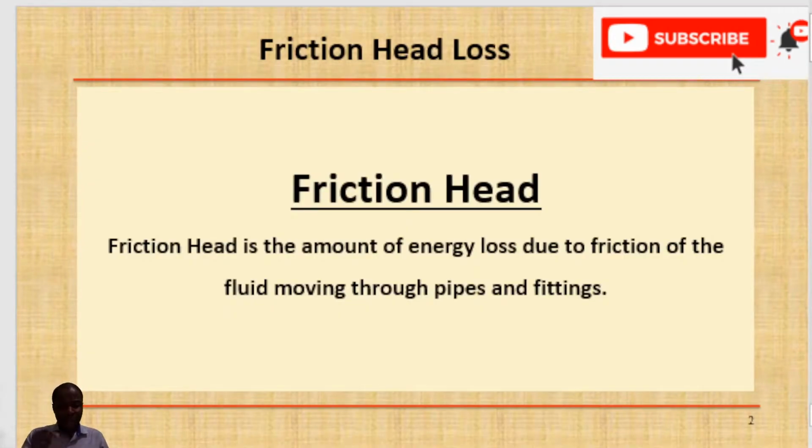Now I want you to understand that by increasing the flow rates in your pumping system, this will introduce friction into the system as your liquid is traveling along the pipes from the suction tank to the pump and from the pump into the discharge pipe. So definitely there is going to be friction in the system.